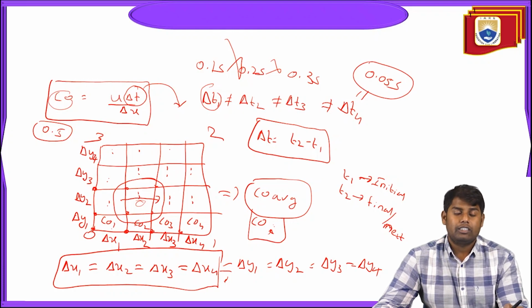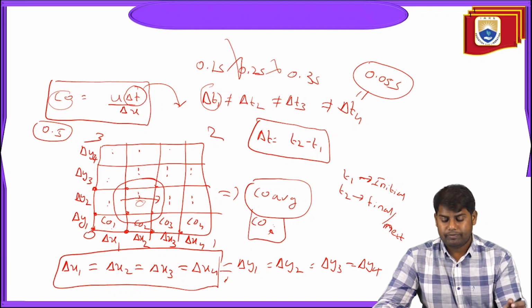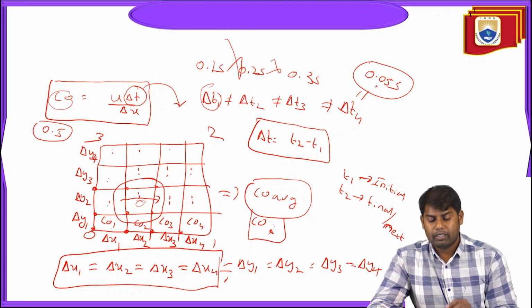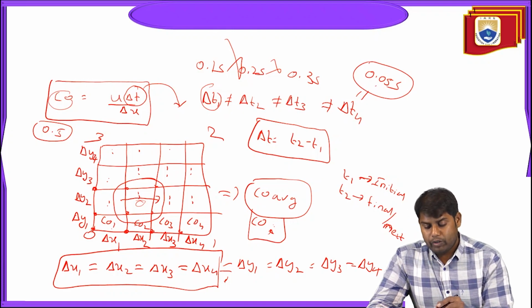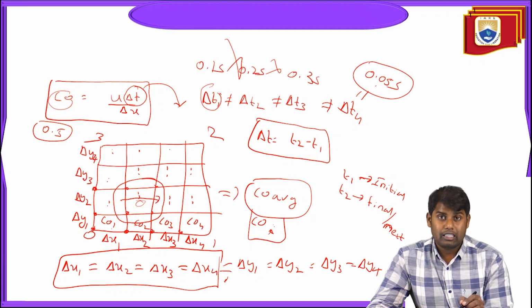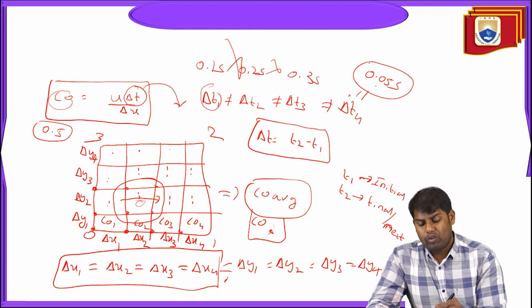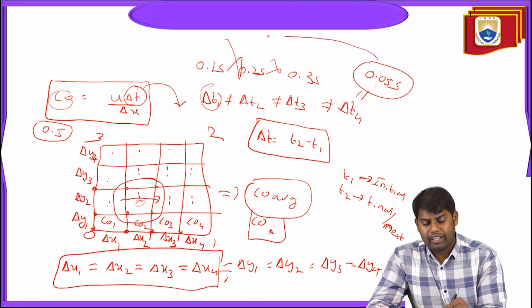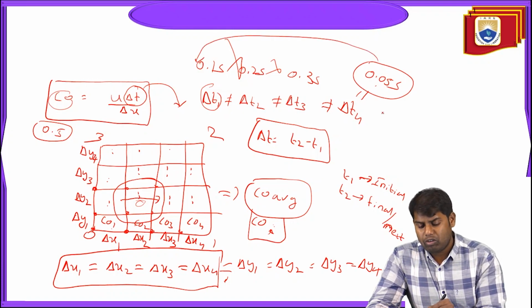When you decrease the time step, if the simulation results are converging, in the sense, if the results are getting steady state at lower time step, and when you take delta t and delta t1, if the results are nearly equal, you can consider delta t1. Now even if these two are not matching with each other, you have to go for another thing.